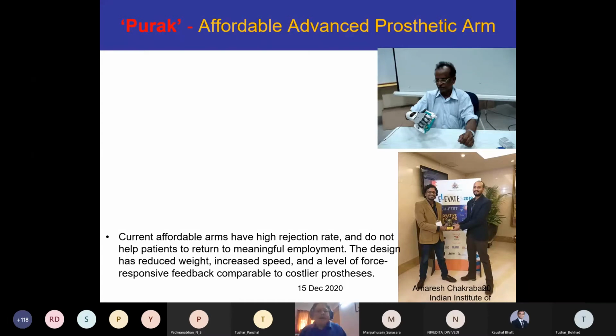So they wanted to have a prosthetic arm that will use only a single actuator in order to operate all 5 fingers in a manner that allows them to wrap around arbitrarily shaped objects. That's a very difficult task. So they used a principle called under-actuation with which they were able to do that. And the number of actuators roughly is proportional to the cost of the device.